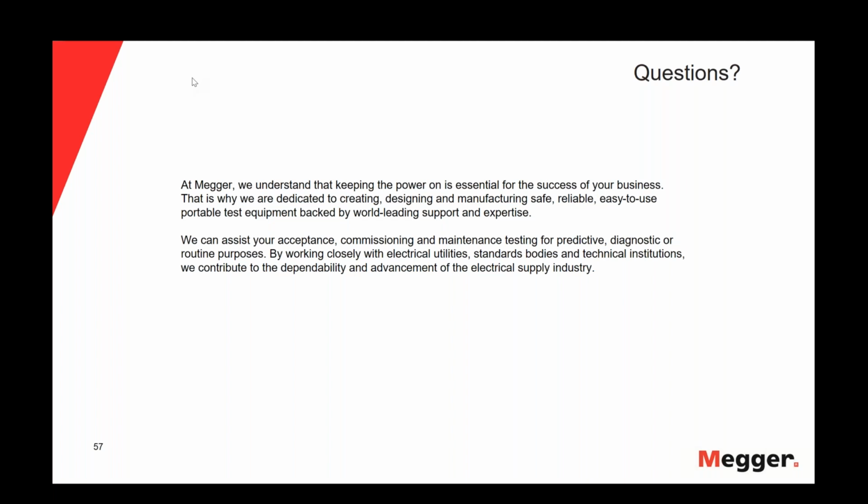With VLF and Tan Delta trending, you are looking at the Tan Delta staying flat and not having an increase. If you see an increase, that is a clear indication that something is happening in the cable while you do the withstand test, and normally that is nothing good. So I think it's a good test. The monitored withstand test is something that should be explored much more overall. Just a brief comment on it: you can use either Tan Delta, you can also use PD as an indicator, or you can also use leakage current if you use the cosine rectangular waveform like Javier was talking about.